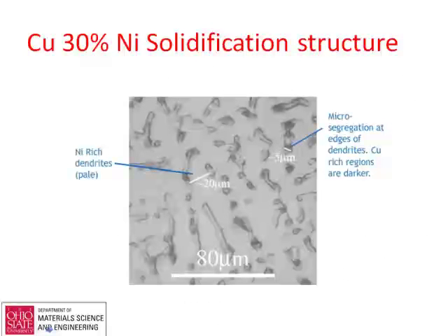And the first bit to solidify are these nickel-rich dendrites along the middle. Okay, so these are the nickel-rich dendrites, and then these are the last regions to solidify, which are the copper, which are swept to the side. And that's what you end up seeing. So you get this segregation. Again, it's a mixture of regions of different solid solutions that you end up getting.